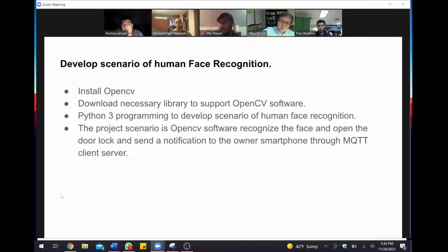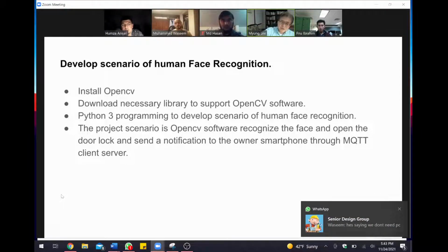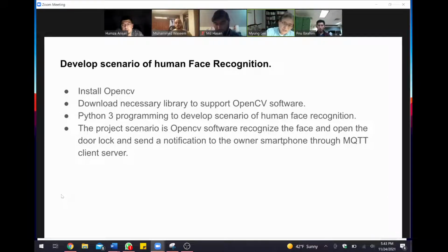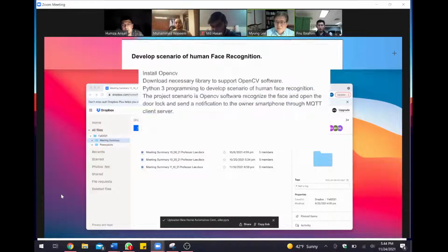And the ESP32, upon receiving the MQTT message as the client, will convert that into some action using the relay, something like that, right? Or you read the current state from certain sensors. That's basically what you do.